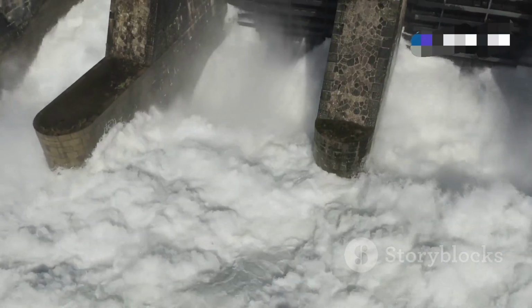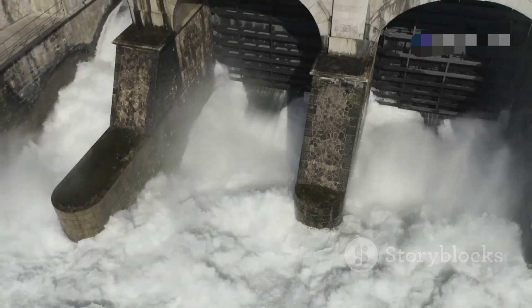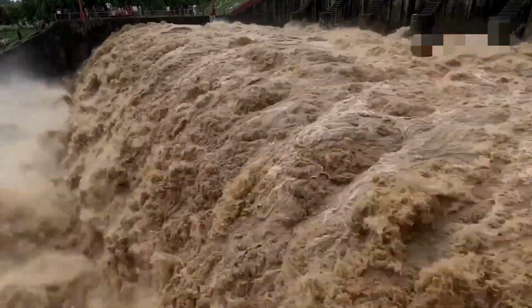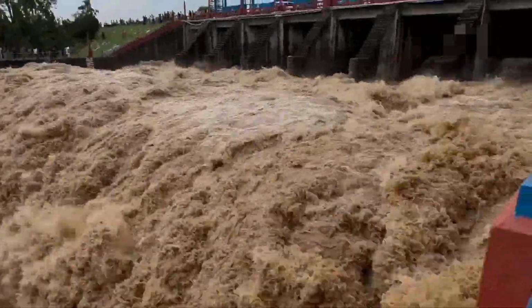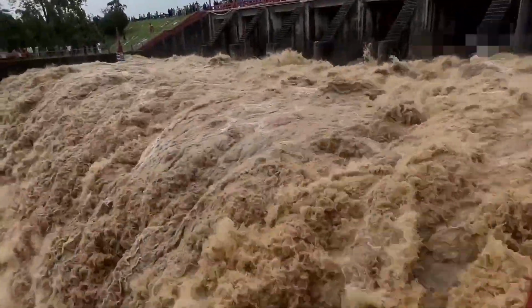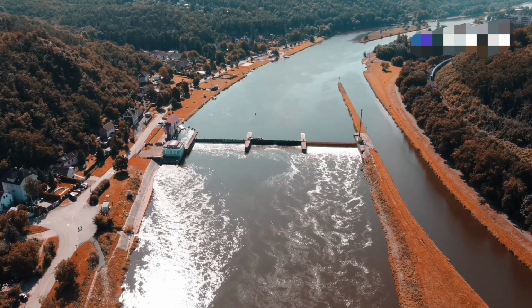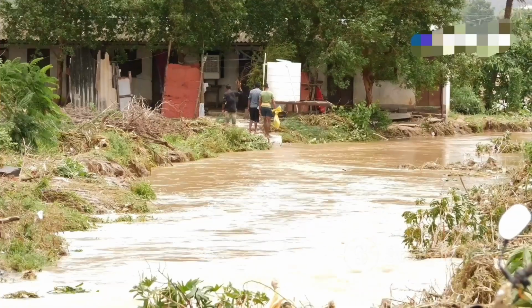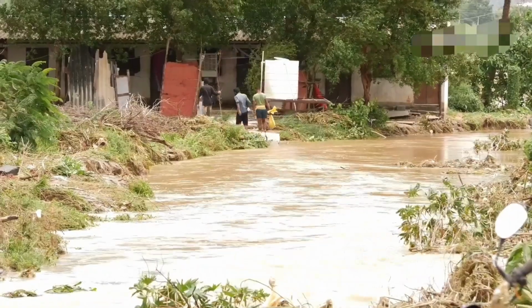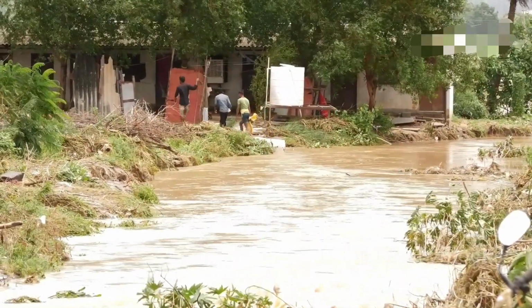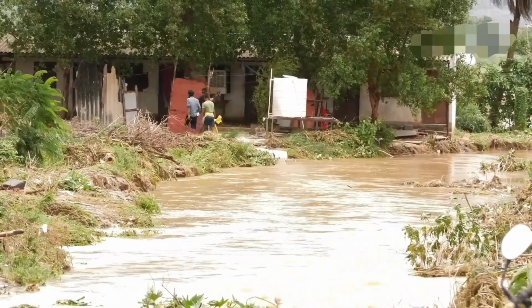A very rapid breach development will lead to a sudden release of a large volume of water. This creates a flood wave with a high peak discharge and a steep rising limb on the hydrograph. Conversely, a slower breach development allows the water to be released more gradually over a longer period. The breach development time directly impacts the peak outflow from the dam and the warning time available for downstream communities.